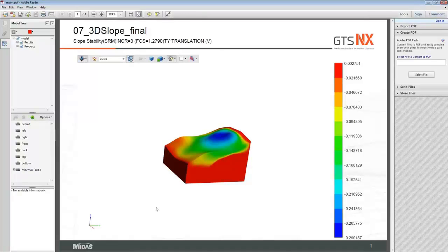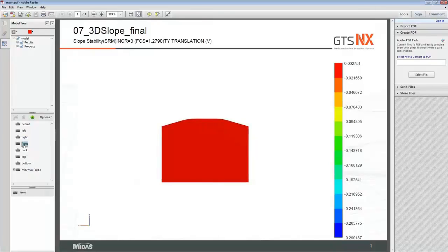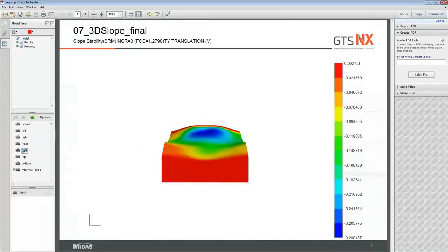Now whenever we do the finite element analysis, we need to consider a particular view of that model, so working with the model to generate the report becomes very tedious. So what you can do is rotate the model within the PDF itself and just save it for your report generation, which will be directly in PDF format.